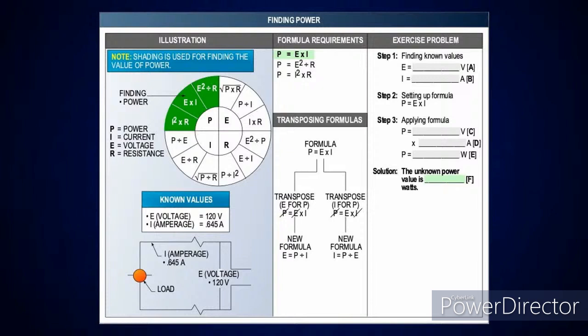Every time I look at calculations, and basic calculations, it doesn't deal with code, I'm always looking at how somebody will understand this to where it's easy to understand. One of the main things I look at is, when do I multiply, when do I divide? When I'm looking at power, that's what I'm thinking. That's something I put in my mind a long time ago: E's above R, so therefore I'm going to square that. And if I have the amperage, I've got to square it, but I'm going to multiply it because they're across from each other.